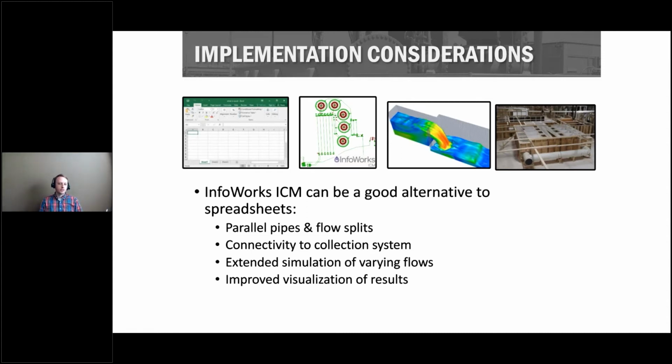Thinking about CFD modeling, ICM wouldn't necessarily replace that in any way. ICM is not going to give you a really good hydraulic representation of a big vortex drop structure or something like that. You might still want to push that to CFD modeling, but for higher level, simpler hydraulic modeling situations, ICM can be a good solution.